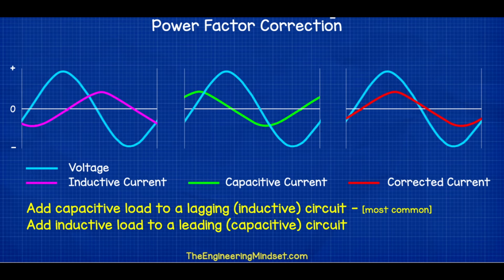If theta is 0 degrees, cos 0 degrees equals 1, and the system is 100% efficient. If theta is 90 degrees, cos 90 degrees equals 0, the power is purely reactive and no useful work is done. For a given load, the current is inversely proportional to the power factor. A low power factor means higher current. To avoid this, engineers use power factor correction by strategically adding capacitors to balance the inductive reactive power, driving the phase angle closer to 0 and the power factor closer to 1.